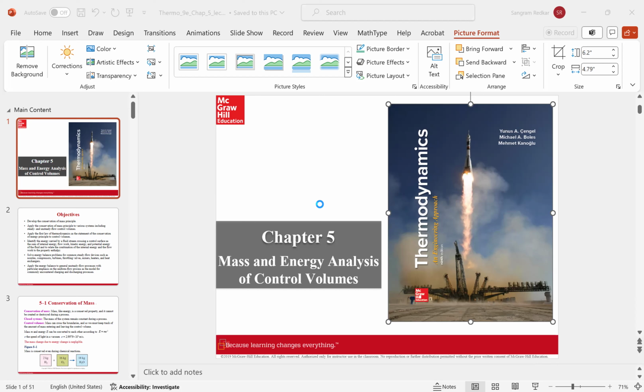Same thing, if you look at the diffuser, you write down the equation for the energy balance, and if you have an adiabatic diffuser, which means there is no heat transfer, and if there is no work done, it means all the change in the enthalpy is because of the change in the speed or change in the velocity. So the flow accelerates inside the nozzle because the exit velocity is much greater than the intake velocity. This is a very simple example.